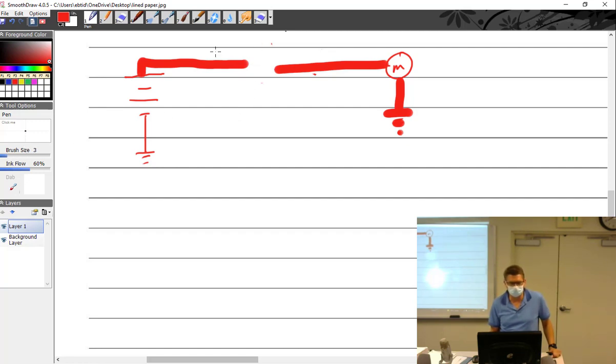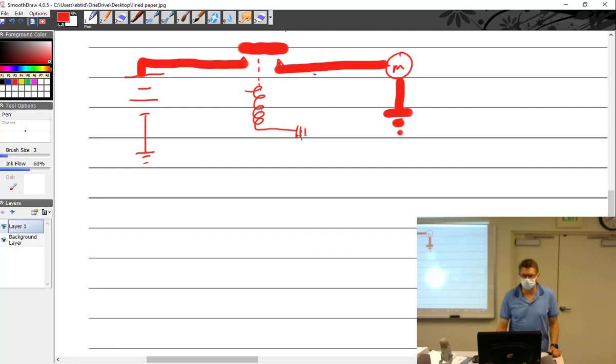So what I would do is I need a relay. So the relay is going to have a big old fat bar up here that can move up and down, based on an electrical coil that is going to create an electromagnet that when it's energized, it will pull this bar down. We'll make that a momentary contact. We'll pull that bar down and complete the circuit. So all I can do is push this little bar down. Okay, it's a bridge. Yeah, it drops the bridge right on there, and then all the little electrons are little cars, and they go across the motor. Sure. All right, that's all I get.